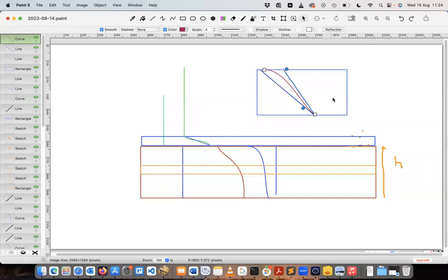If it's the case that this component can diffuse very rapidly through this medium, then it may be true that component A very quickly achieves its new steady profile. So instead of our concentration profile taking a long time to transition and settle out to the new steady state, we could say, well, then we don't need the whole unsteady state balance.